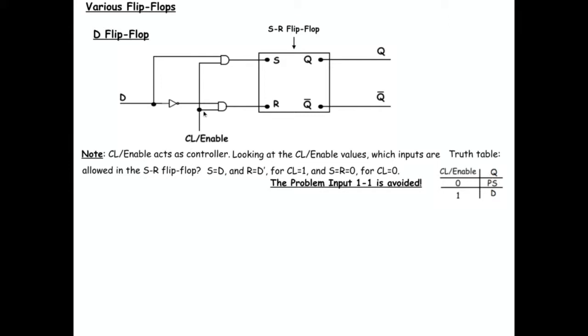However, if the clock is on, ding, then the flip-flop gate, the Q, assumes the value of D, whatever that value is. So in real life, the clock or the controller will have two outcomes, previous state or value of D. Of course, previous state is some value 1 or 0, and D is also some value 1 or 0. Any questions about this?